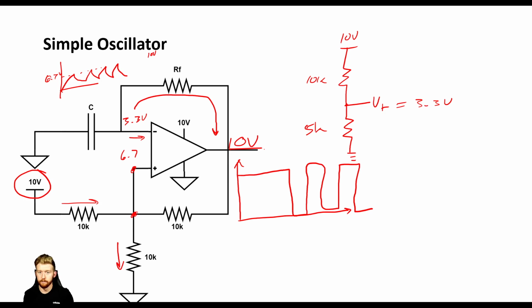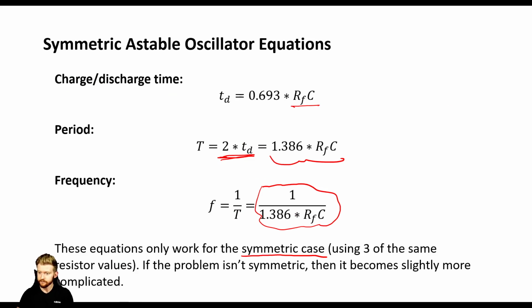and 5 components. So if you do have the components, I do encourage you to make it, and if you don't, plug this into LTSpice. See if you can get a simulation that shows how this is all working, okay? Because this is actually a pretty important understanding. You can probe all these different points to see maybe how this capacitor voltage looks, and maybe the effect of changing a bunch of these different resistors or changing the feedback resistor, stuff like that, okay?